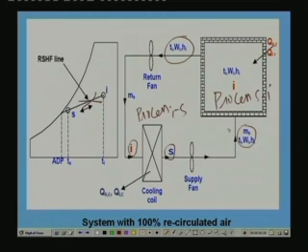As the air flows through the conditioned space, it picks up sensible heat and latent heat. That means its temperature increases and its moisture content increases. And the same air, as it flows through the cooling coil, its temperature reduces and its humidity ratio also reduces, because we have to go for a cooling and dehumidification process in the cooling coil. So as far as the conditioned space is concerned, it is heating and humidification, and as far as the cooling coil is concerned, it is cooling and dehumidification. If you plot these two processes on the psychrometric chart, they exactly coincide. The only thing is that the direction will be opposite.